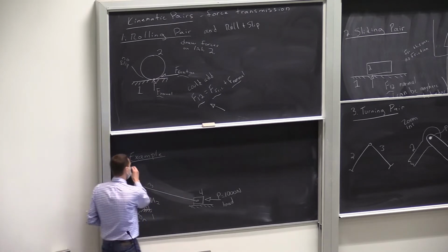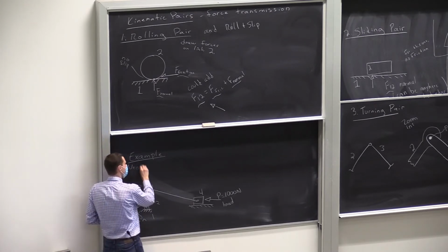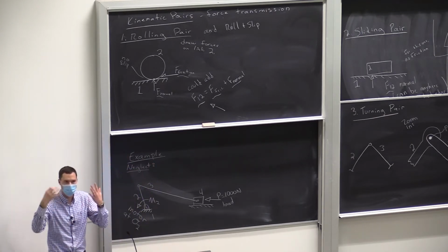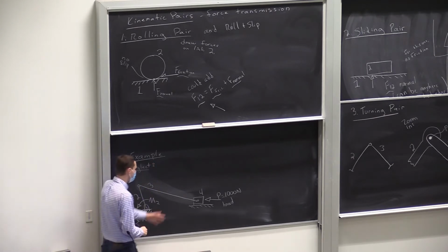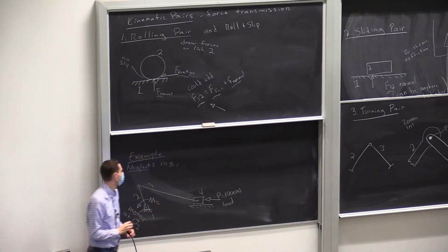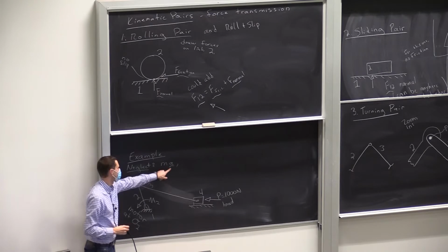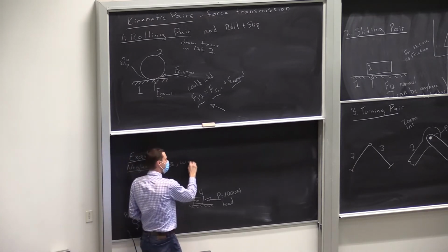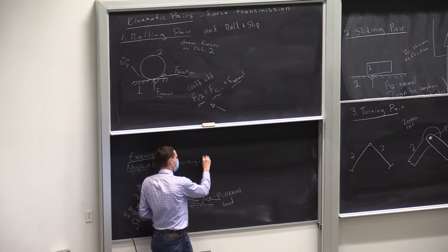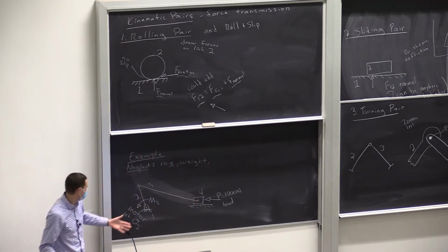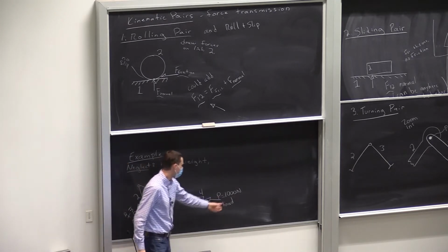Okay, for this example, let's neglect some aspects. Let's neglect a couple forces. We talked about a whole bunch of possible forces, so let's assume that there's no acceleration. So mass times acceleration, we're going to say that's really small. The links have no weight. Maybe they're very lightweight compared to this big load, 1,000 newtons.